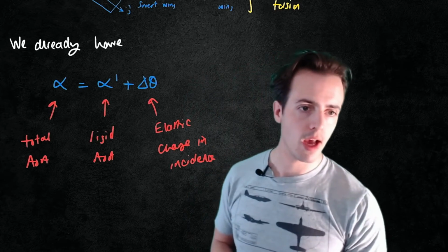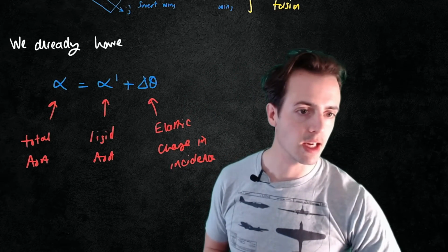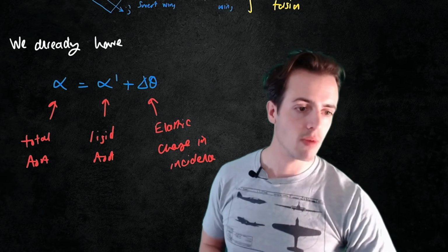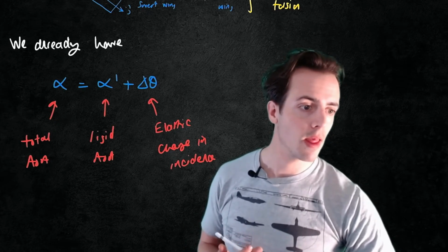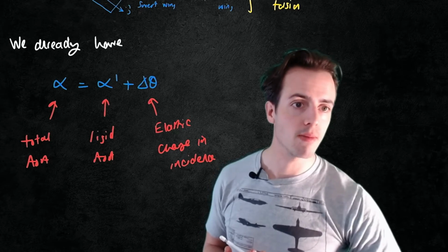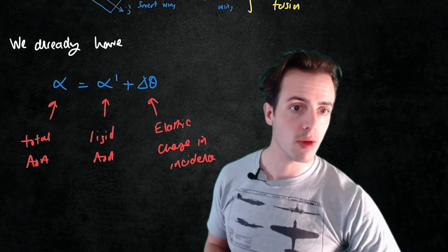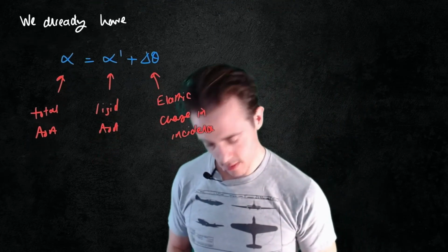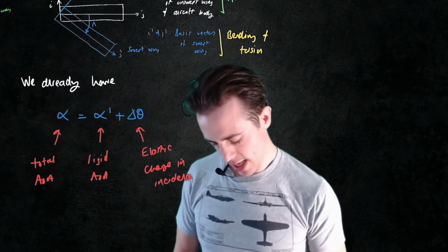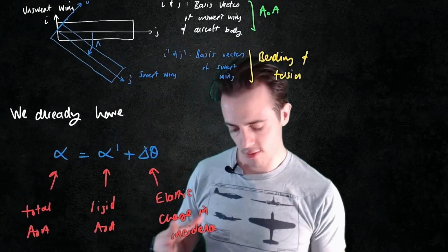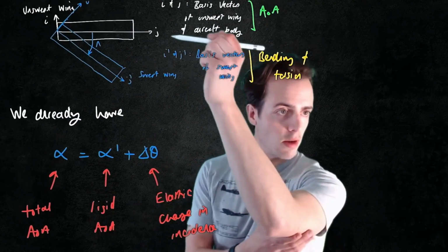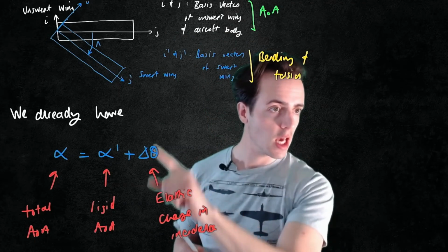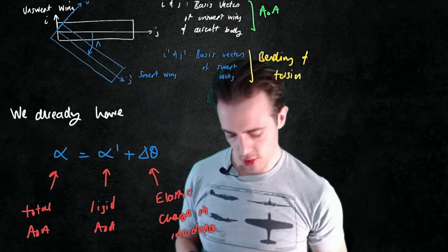So this expression, as I've written it here, is actually only valid for a straight wing. And when we introduce sweep to this problem, then we have to change the mathematics slightly to accommodate sweep here. So we need to then look for what's the effective rotation about this J, okay, because that's the angle that we care about, if we have both bending and torsion occurring.